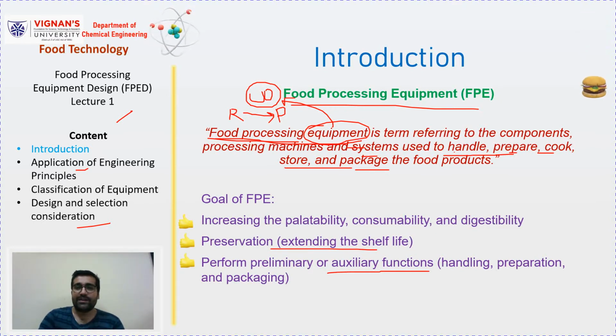If we take unprocessed milk, the shelf life of the milk can be 6 to 8 hours. But if we sterilize the milk with the help of a sterilizer, the shelf life of the milk can be extended to 6 to 8 months. The condition is that we have to pack it in hermetically sealed packs, like the Tetra packs. So we need a packaging equipment as well.